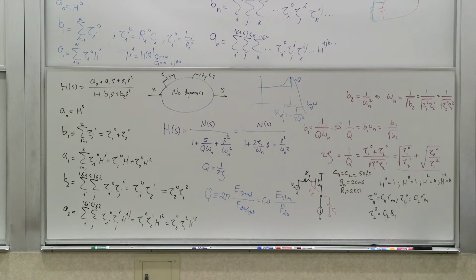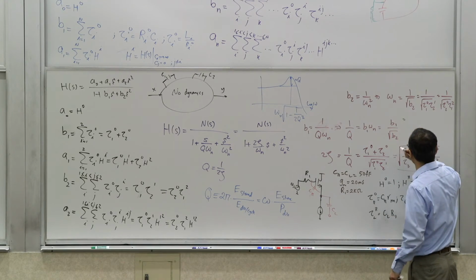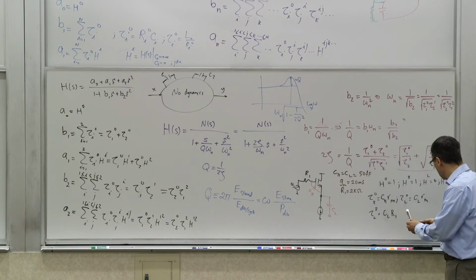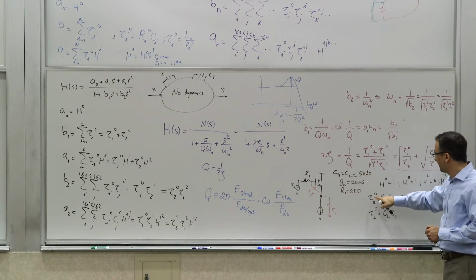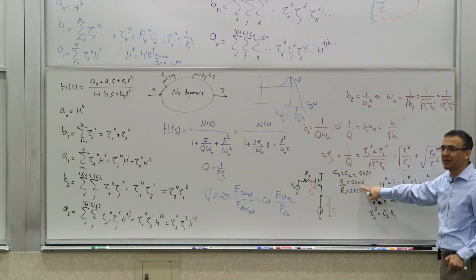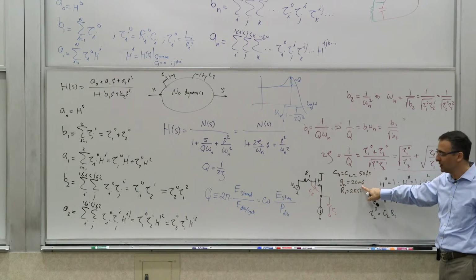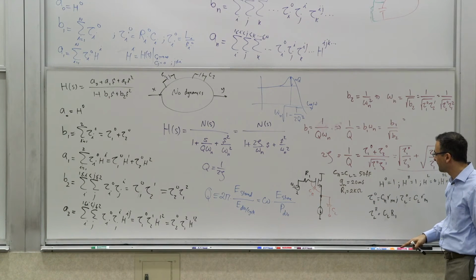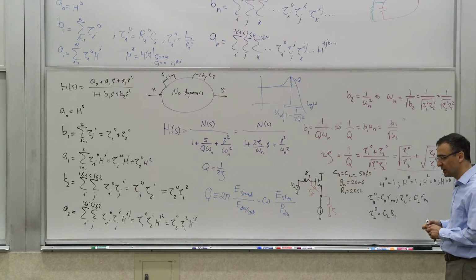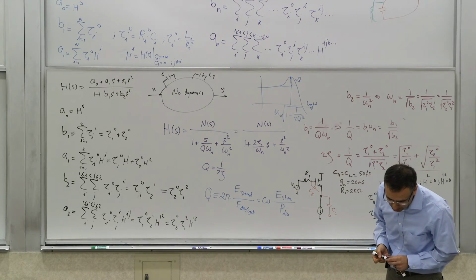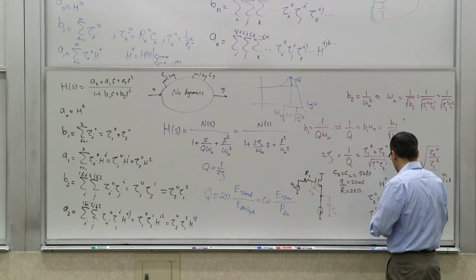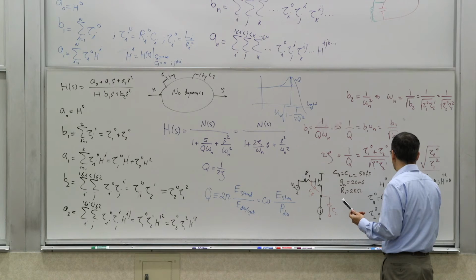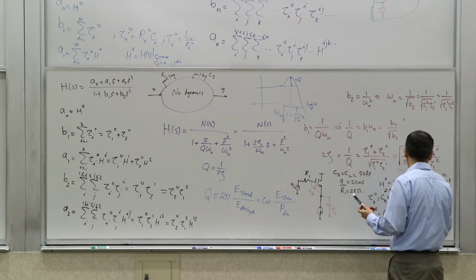So we can put them together and all those things, but let's plug them into these guys and see what the numbers would be. So in terms of omega n, what we need, and let's put some numbers here, by the way. We said these are both 50 femtofarads, and 20 millisiemens corresponds to 50 ohms, right? So 50 femtofarads and 50 ohms is 2.5 picoseconds, right? Each one of the time constants is 2.5 picoseconds, I believe. Yes. So this is 2.5 picoseconds. And this is 2.5 picoseconds.